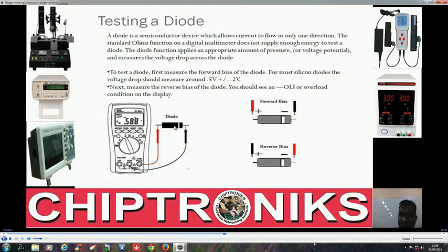A digital multimeter has a very good utility present in it that we call the diode range. But people are very much confused about what exactly is displayed on the LCD display when we are measuring a diode. Basically, the diode range measures the junction potential between the P side and the N side. So the diode range measures the junction potential.